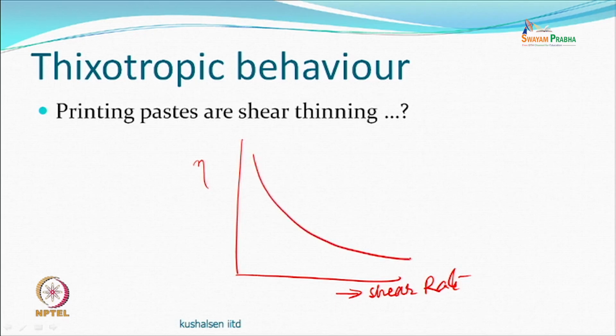This phenomenon is seen with the printing paste. It is seen in polymers which are melt spun, and in polymers which are wet spun. Why it is important is that if the viscosity does not go down because of the shear, the amount of force required to push it through the holes or pores will be very high.